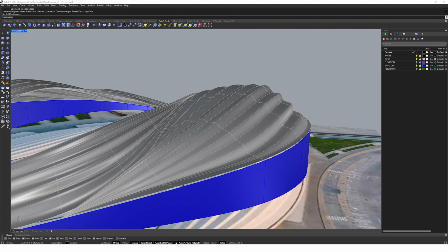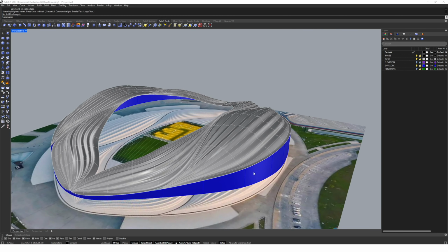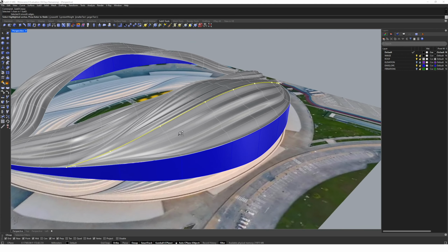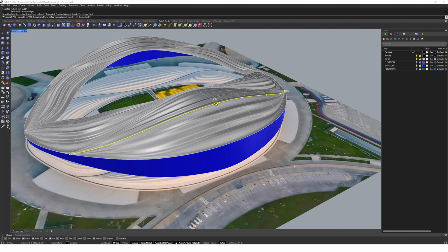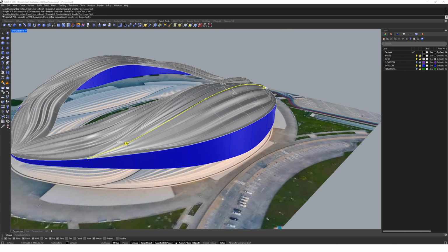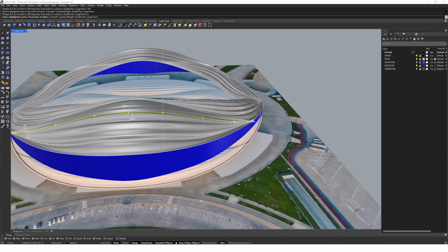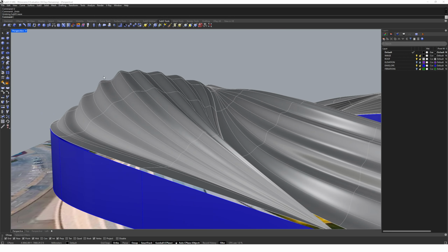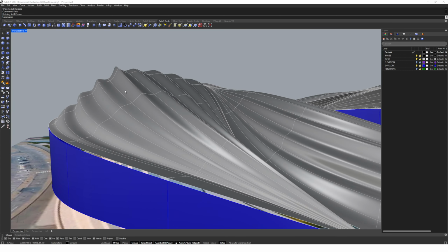A small but powerful update to the sub-D modeling toolkit is the extra customization of sub-D creases. You can now control the crease strength of your geometry and create better transitions between smooth and hard edges in your model. If you double-click along a sub-D edge and use the sub-D crease command, you can specify specific vertices with a number between 0 and 100, 0 meaning no crease and 100 meaning a full crease, and create a transition between no creases and full creases along your edge. This gives you the ability to create blended creases in your geometry, which can help fade hard edges into soft edges.